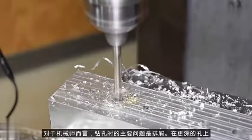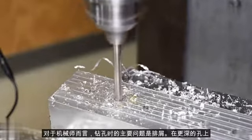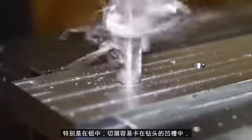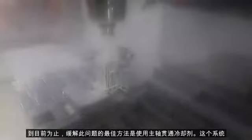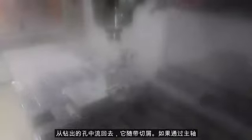For the machinist, the primary concern when drilling is chip evacuation. On deeper holes, especially in aluminum, chips tend to get stuck in the flutes of the drill, which dramatically increases the heat generation during cutting. By far, the best way to mitigate this problem is with through spindle coolant. This system delivers high-pressure coolant right to the cutting edge of the drill. As the coolant flows back out of the hole being drilled, it carries the chips with it.